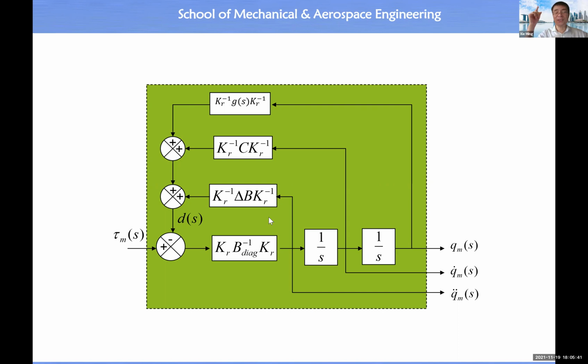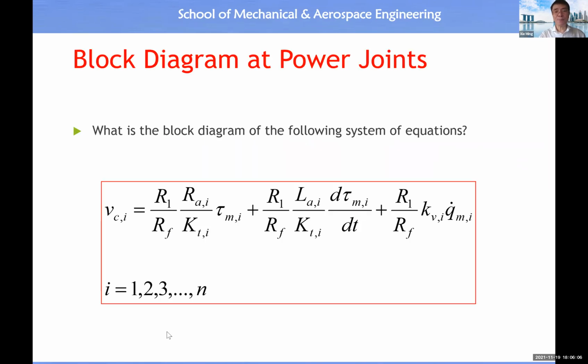Then you can start to imagine how to make this term disappear: choose the speed reduction ratio to be reasonably large enough. That's it. All right. Then you will make the robotic arm behave like an LTI system. So that is the magic in industrial robotics. All right. So this is a very, very important discovery, or information or knowledge, about the design of a robotic arm.